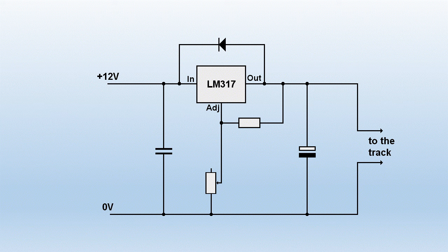Or you may have back EMF from a motor that would make the output pin at a higher voltage level than the input pin. In those kinds of situations, a feedback diode is connected across the input and output, and thereby, in normal circumstances, is reverse biased, but where there's a problem, it's forward biased and prevents damage.